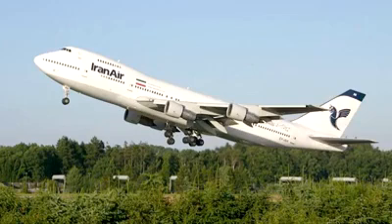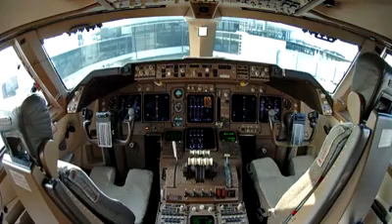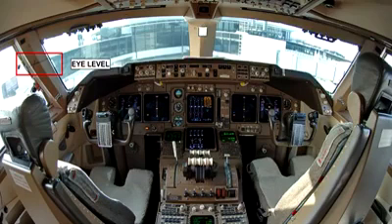The vertical and horizontal angles of the windscreen are specified so that each pilot has a sufficiently extensive, clear and undistorted view to be able to safely perform any maneuvers within the operating range of the aircraft. It is important that the pilot has his seat in the correct position to get a good view forwards and downwards out over the window, over the coaming and nose of the aircraft, without restricting his overall view. To help with this, reference eye points are often painted on the flight deck windscreen frame.